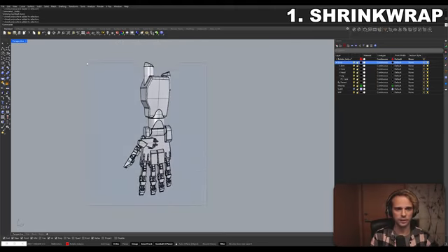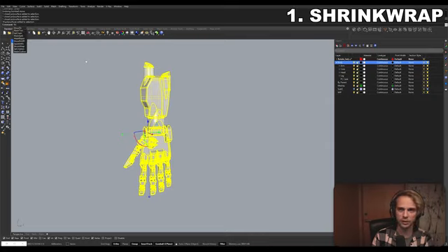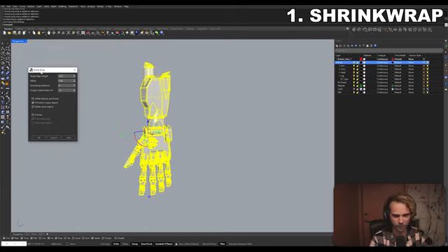Now, if I select all of this and I type in shrink wrap, there we go, shrink wrap, and I specify what's my edge length, basically what's the resolution at which I work. I have no idea what's the resolution here. I'm gonna trust it with 3.62, we'll see. I'll hit preview, I'll let it think.